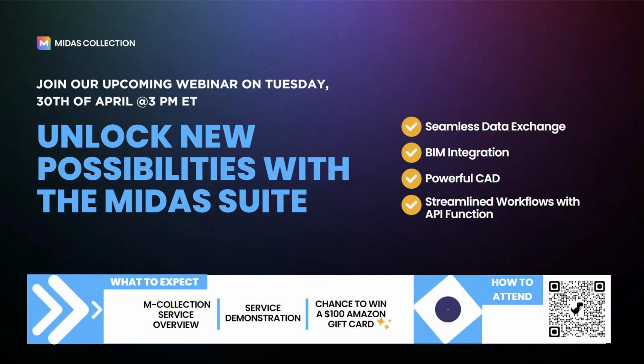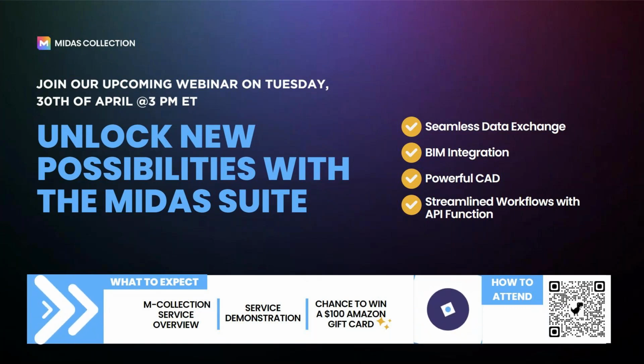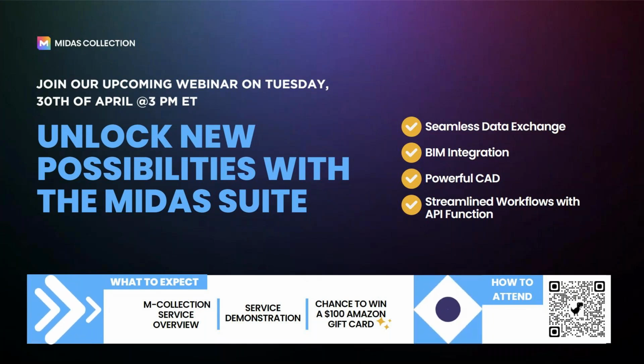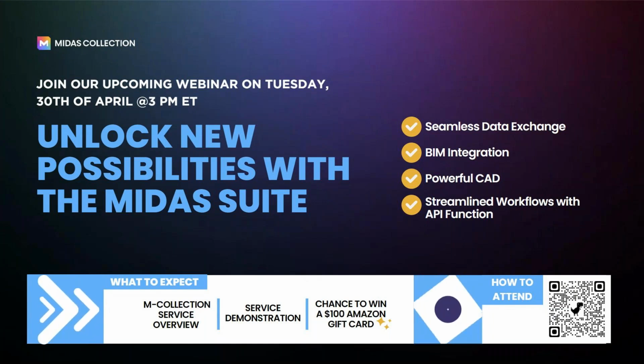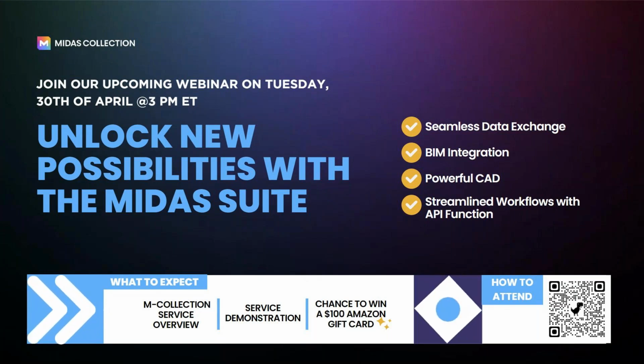So I have another question. Does the Midas also check the AASHTO constructibility check? How does it model the overhang brackets and the screed machine loading? So yes, the program performs the constructibility check as well when you are doing the construction sequencing analysis. As you might have seen, it has the option for the constructibility check as well.